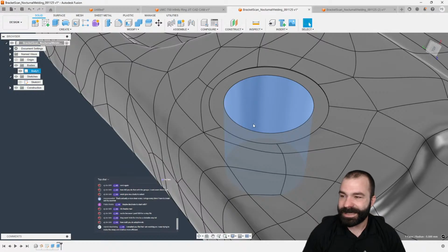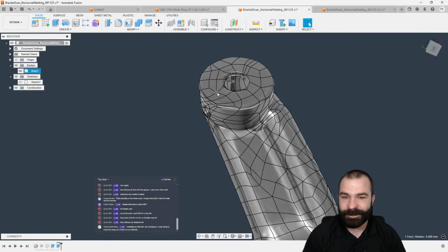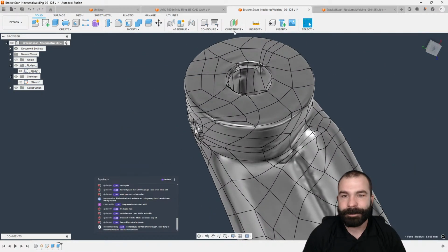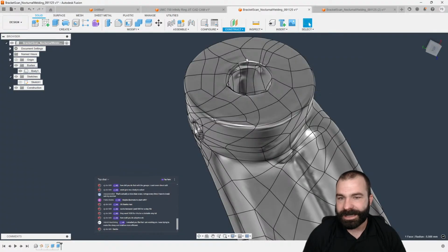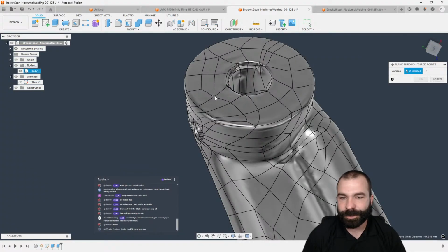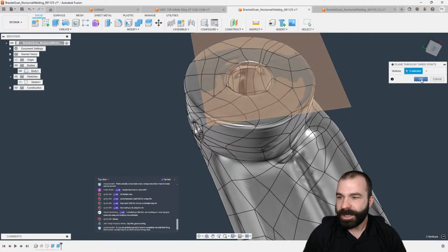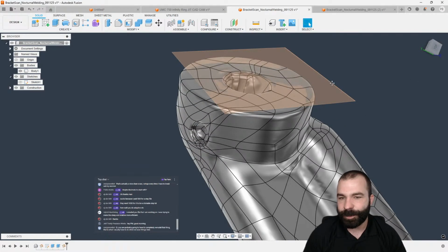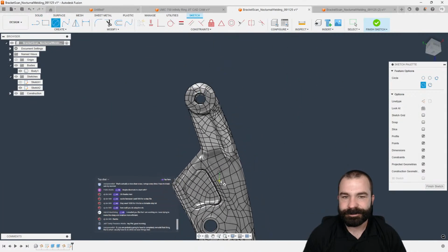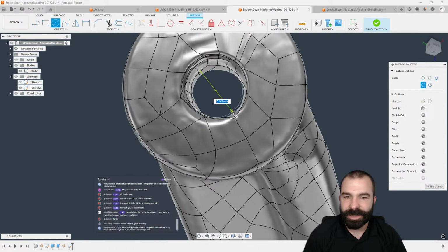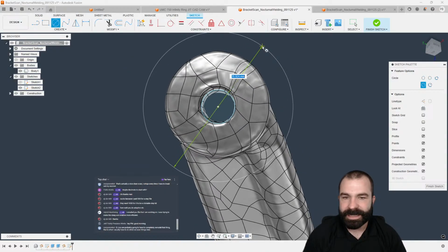But let me know, guys. Is that something that's going to help you out at all, EJ? I mean, again, you could do the same thing up here at the top. Nothing more than like a 3-point plane, I think, is going to be your best bet. Grab your 3 locations. Just like that, I now have something to work off of. If this was supposed to be flat, again, this is nothing more than creating a sketch. Maybe I do a circle at center point and then a secondary circle.